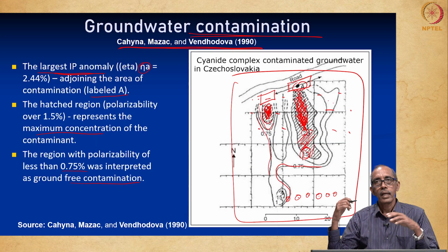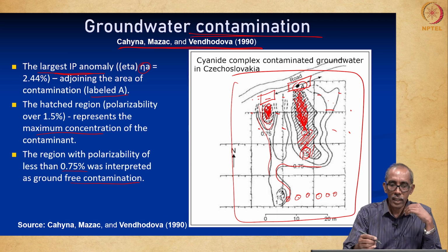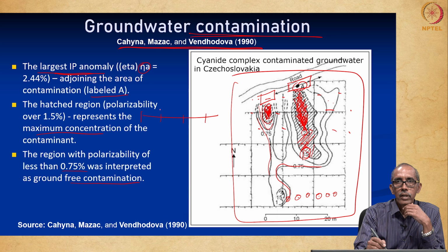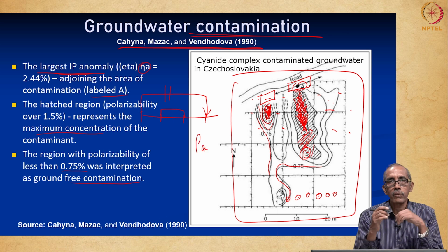So, we have seen how the induced polarization method can be carried out in these two lectures, right. How is this different from the resistivity method? Can you tell me how it is different? In the resistivity method also we used 4 electrodes. I am drawing the Wenner configuration now. In the resistivity method, the electrical potential was measured while applying the current from the battery. While applying the current, we measured the electrical potential, using which we estimated what is known as apparent resistivity.